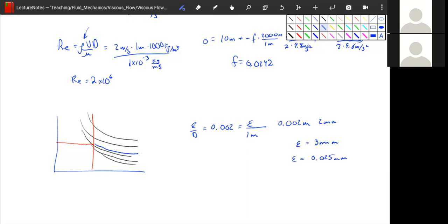So clearly we're getting a lot of losses in our sewer pipe, and it's because our roughness is so large, right? Things get stuck to the sides, and it's really gross and really, really inefficient. So there's a reason why they have to go through and scrape the walls of sewer pipes. Also because as things accumulate on the walls, your diameter decreases. And we've seen how important the diameter is for maintaining high flow rates. Even a small change in diameter can really, really hurt you because your velocity increases. And yeah, lots of reasons, right?